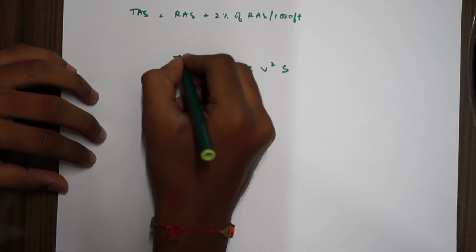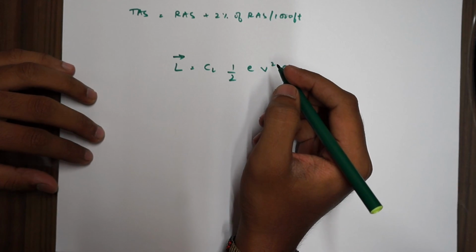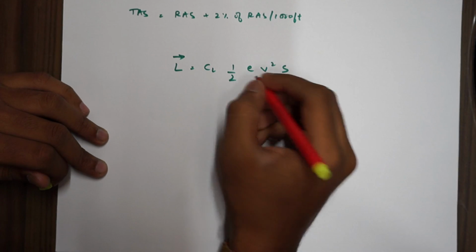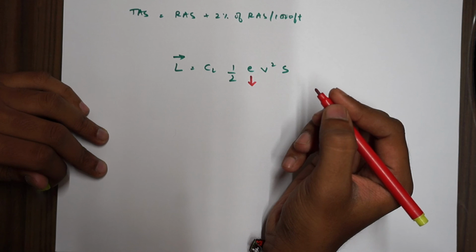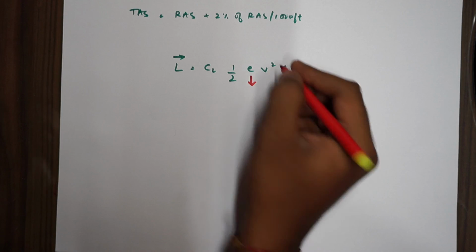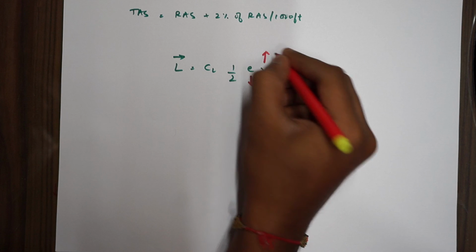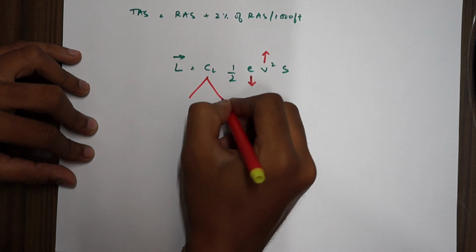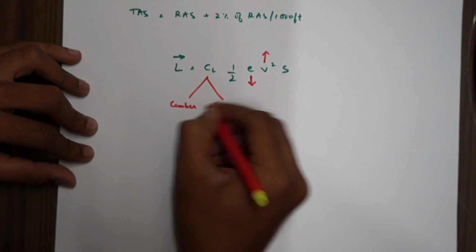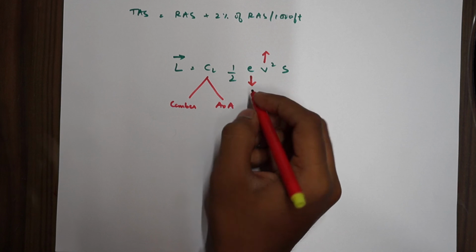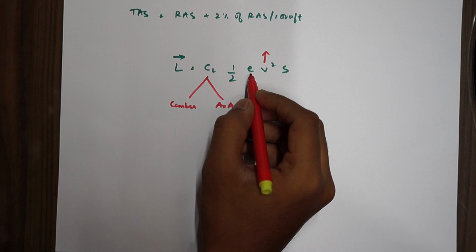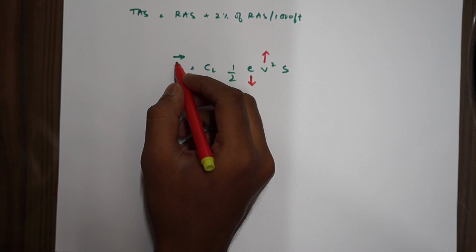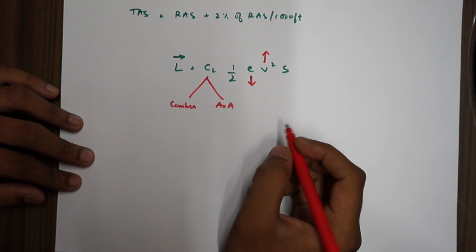Say, suppose for a constant lift, alright, for a constant lift, as the altitude increases, obviously the density will decrease. So it has to be automatically compensated by the increase in TAS. Alright, if other parameters remain constant, that is camber and angle of attack, others all constant, if altitude increases, your TAS has to increase to compensate for the loss of lift. So that sense you will have a constant lift.